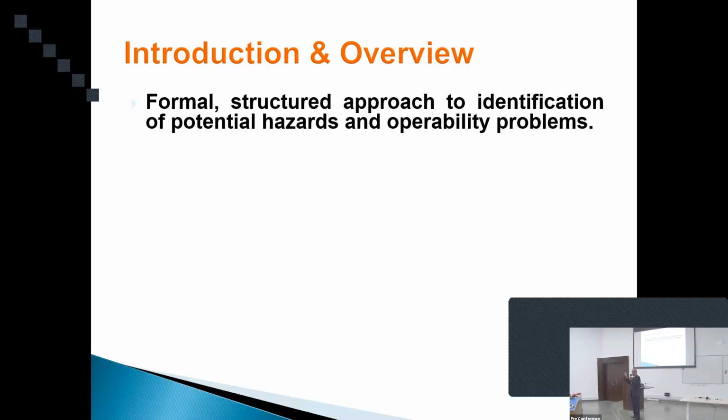So all these things, you have to identify that the safeguards are available. If something happens, is there an alarm to tell? Yes, the pressure is going to go high. Yes, a pressure transmitter will be there. It will give a high alarm. The operator will go and immediately depressurize it, either by draining or venting it out, whatever it is.